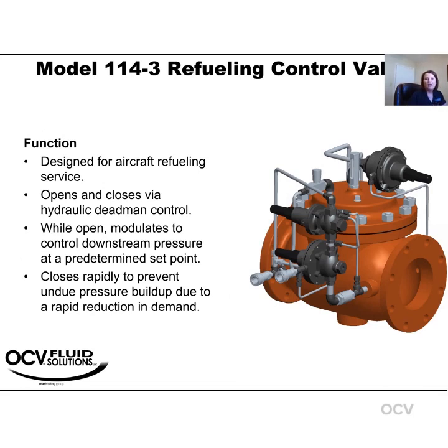While open, the valve is going to modulate and control the downstream pressure using a pressure reducing pilot to a predetermined set point, as well as close rapidly to prevent any pressure that may have built up due to the rapid close or reduction in demand. As you can see here, it's quite the beast, with 3 different pilots on it, as well as your quick connect for your dead man, and then of course speed control and visual indication as well.